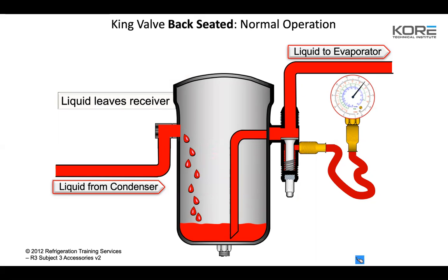If we tell you to crack the valve to take pressure tests, make sure you gauge up to it first, zero out your gauge as always for altitude. And then you're going to turn that valve stem a quarter to a half turn, depending on how damaged the valve is. But if it's a good valve, you should only need to turn that a quarter to 2/3 turn, and you're going to be able to get a pressure reading off that king valve.